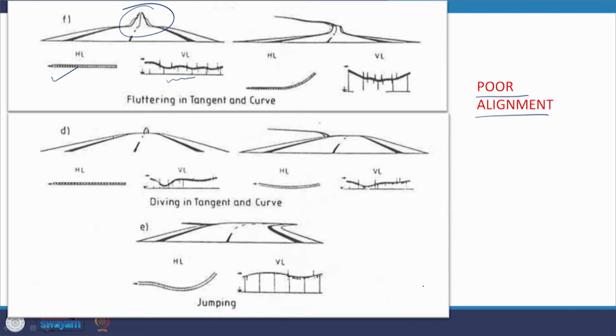Similarly, in this case the horizontal curve is taking a radius. So, it is turning left when you are coming from this side, and then again you have a number of such changeovers in the grade lines. So, you are going in the direction, you are having ups and downs, and at the same time it is taking a curve. So, what happens is that at some point of time it feels like it is closing out, and then it gives a changeover in the form of a line towards the other side. So, this is again not a good way of viewing that particular road.